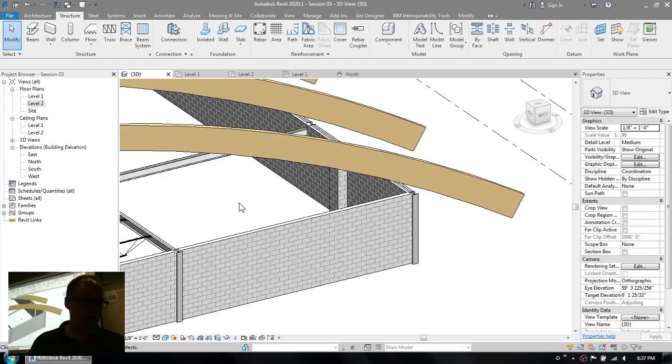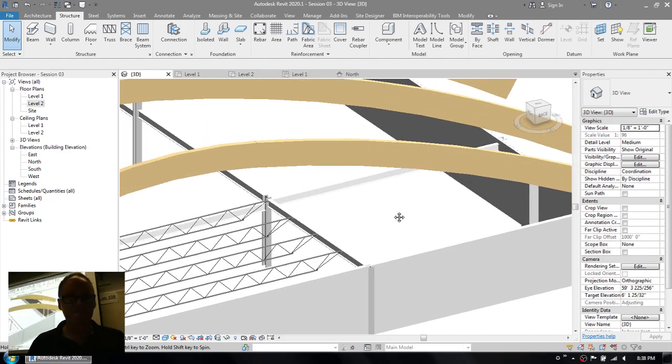So what we did instead is we have voids that are in those families that we can turn on, and when we hit the checkboxes to turn them on in the family, it brings these voids in so that they cut the solids. So that's just a little introduction to how this is going to work. Later when we do the exercise together, you'll see how those voids work. I'll show it off. Now let's go over to the next page here, talking about braces.